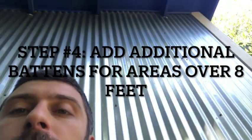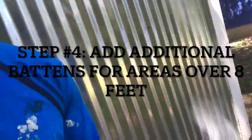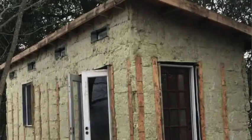Once you get all of the mineral wool bats installed up to the end of the 8-foot long strip, you're going to need to obviously cut some shorter strips for up there. So for example, this is a 13-foot long wall, and then this side is 8 foot. So I was able to get a whole wall worth of mineral wool battened down on this side because it's 8 foot. But over here, I was going to have to add some battens to the top there to cover the gap of any of the battens that are being held above 8 foot.